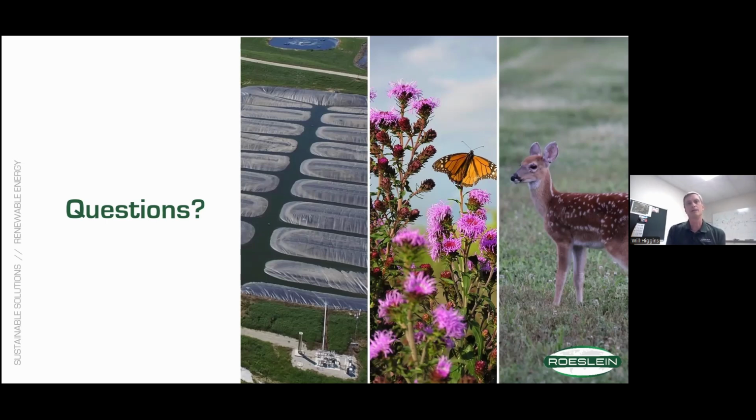But on a lagoon digester, that knee in the curve is less pronounced. And so you need more residence time to get the same amount of digestion. It takes longer. So that's why we get to that 120 days of residence time versus a tank digester. So 4 times more residence time. And it depends on where you are in the country and its temperature profile. So it is temperature dependent, and we develop a curve based on the temperature profile.